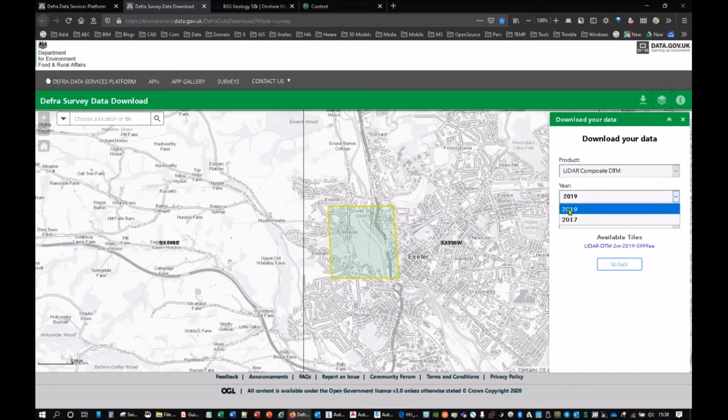You can see when it was collected, in 2019, and you can see you've got different resolutions in here. So let's think about what that means. If you were to get the free data from the Ordnance Survey, yes, it's up to date and good quality data, but the free land data is on a 50-metre grid. So it's quite large scale. It's good for mapping out counties and countries, not so good for mapping out something this small, because you'll only have about 20 dots along here and 20 down there. So it's not great for that.